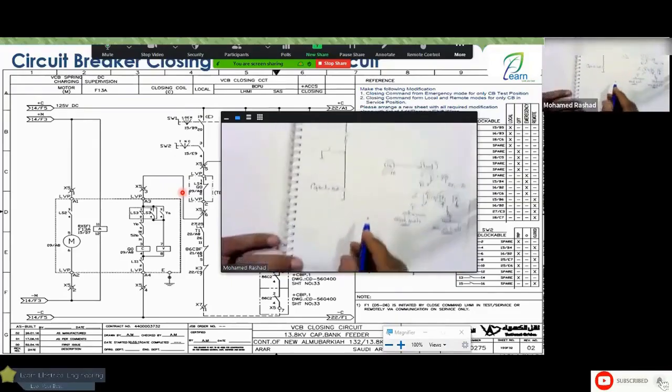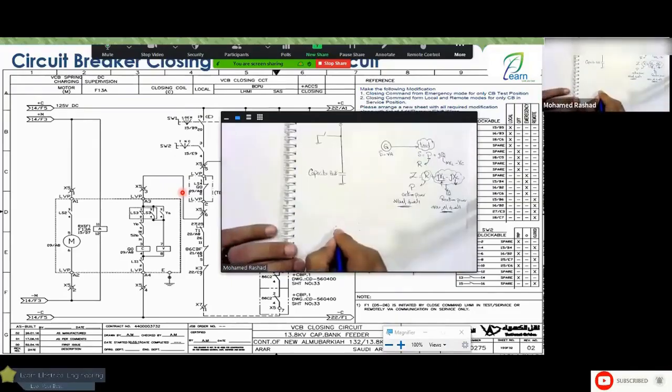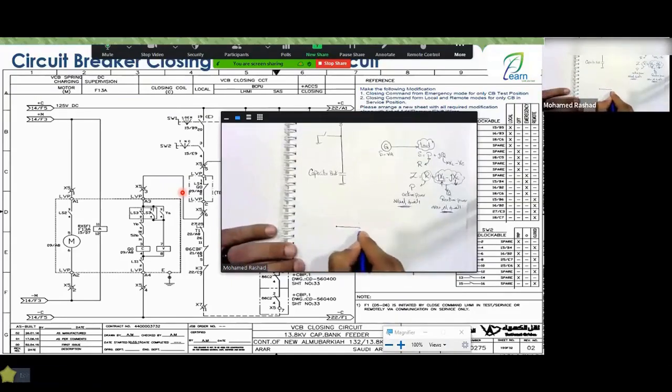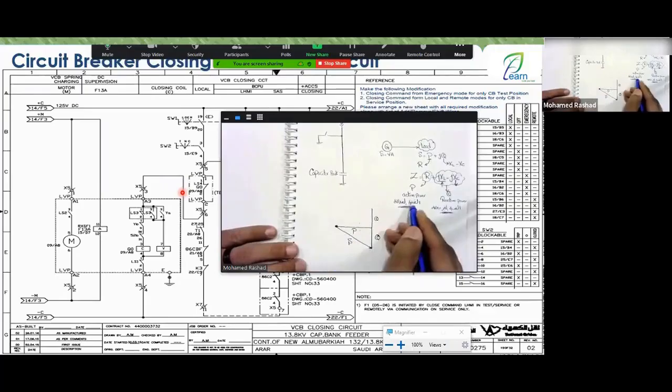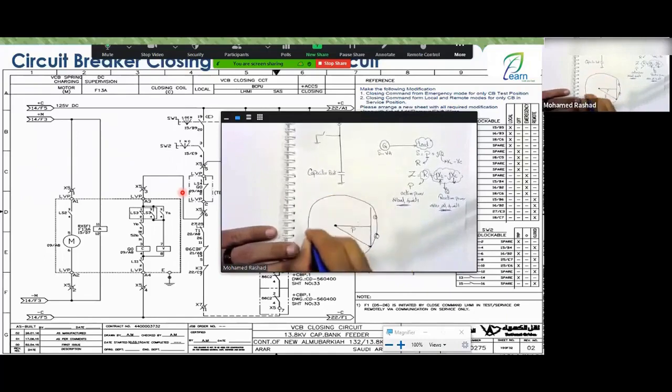All right, so now engineer, you have this generator that produces P and Q, add P and Q like this. And here's your total S. This is P and this is Q, and here's the total S. This S is constant, meaning this generator produces a constant S. Let me draw something like a circle around it, and this is your center, all right? So the S is constant.